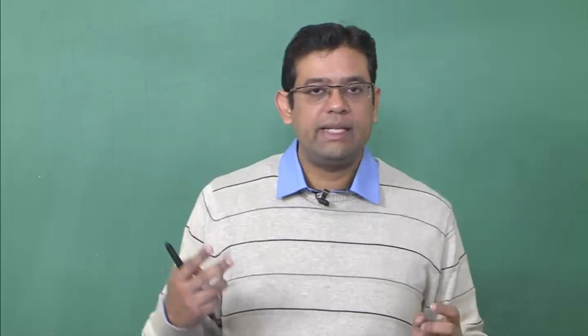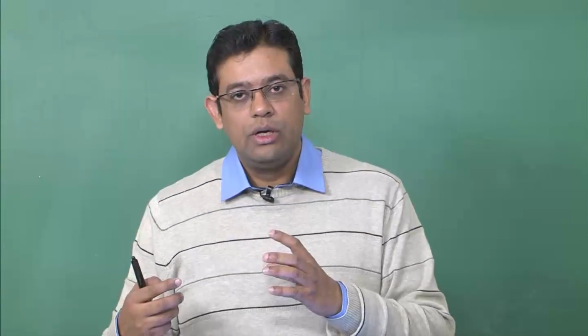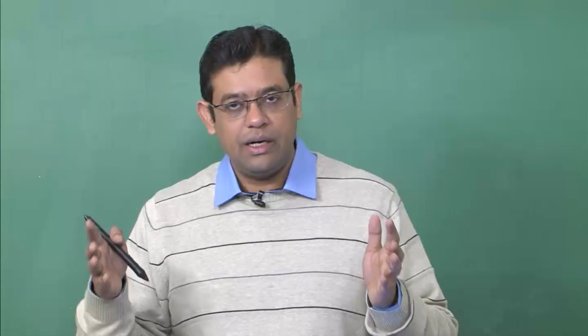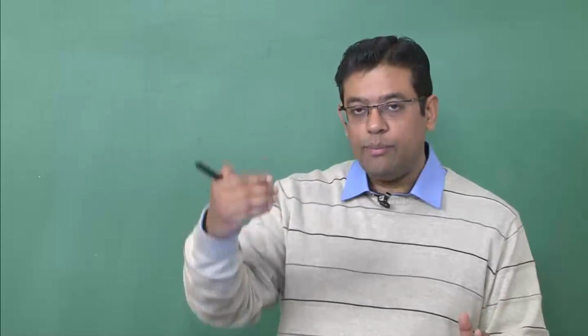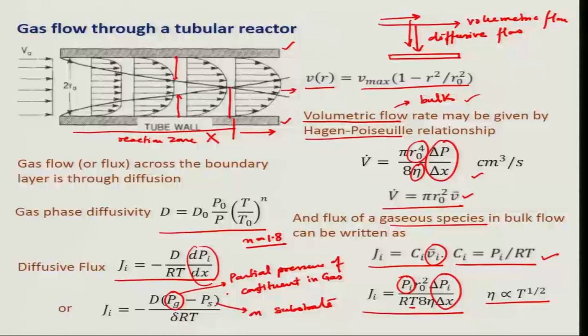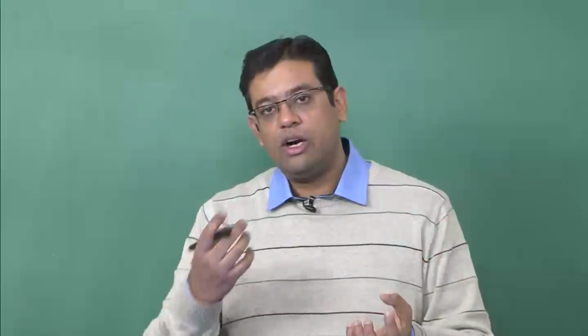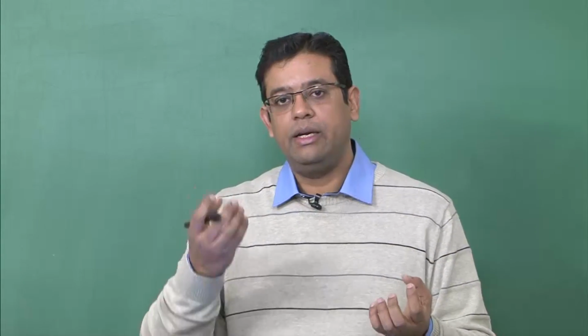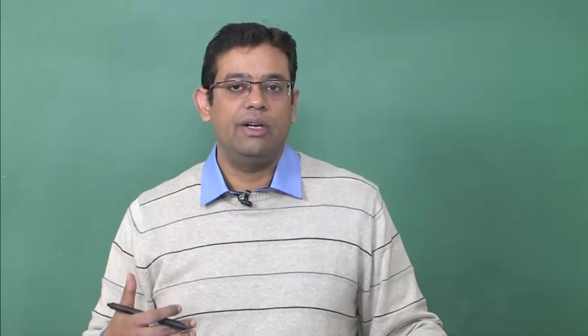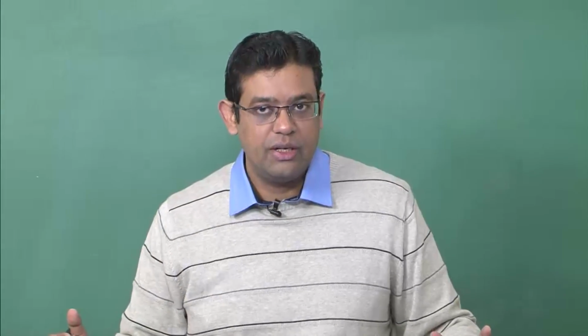I will have two gases in my bulk flow, okay. Both silane and hydrogen will be pre-mixed and sent inside the reactor, okay. And both of these should reach the surface of my substrate in proper amount, where they will react and form silicon, okay. But if one of the constituents is not reaching the surface of my substrate in adequate amounts, then my reaction will not proceed and it will not result in thin film deposition, okay.